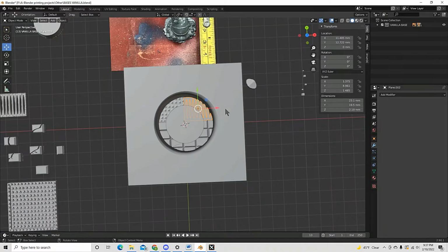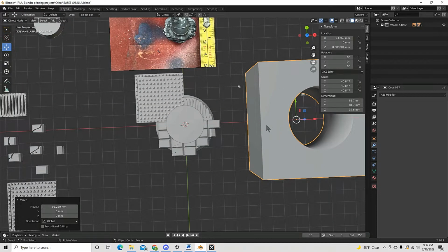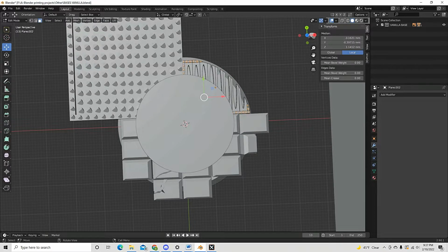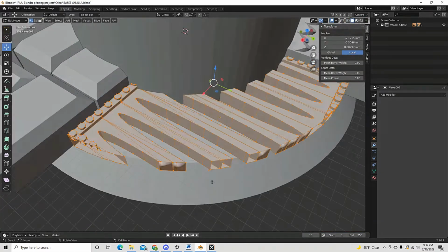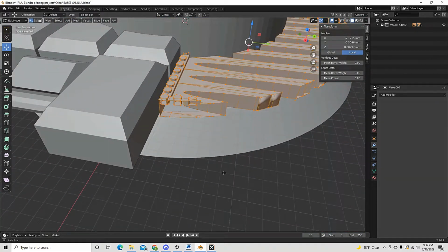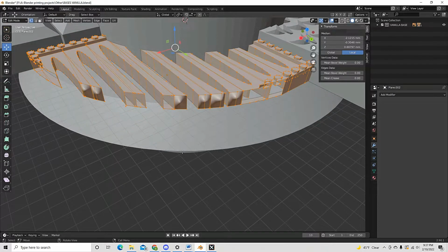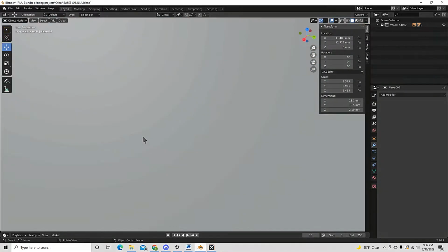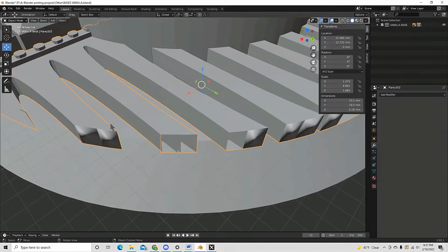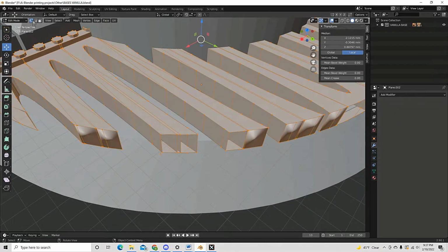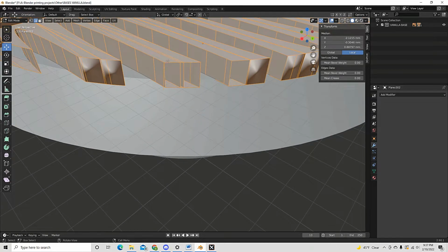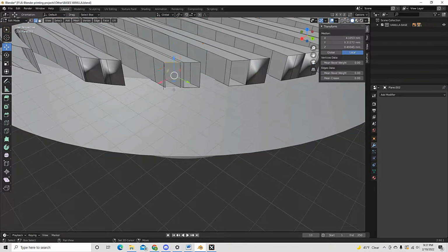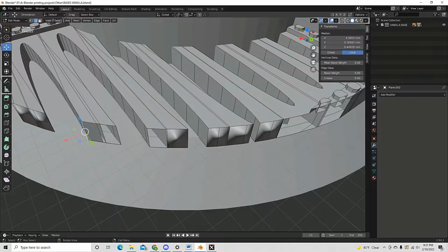Wonderful. However, we gotta do a double check. I'm gonna click on this, press Tab, go to E, press A to select everything, and press this for the vertices. If we see anything flying off, so here are some of the small issues, which is this. I haven't noticed it, but there are now holes everywhere. Oof. And so we have to fix this, and like these stray lines, edges.